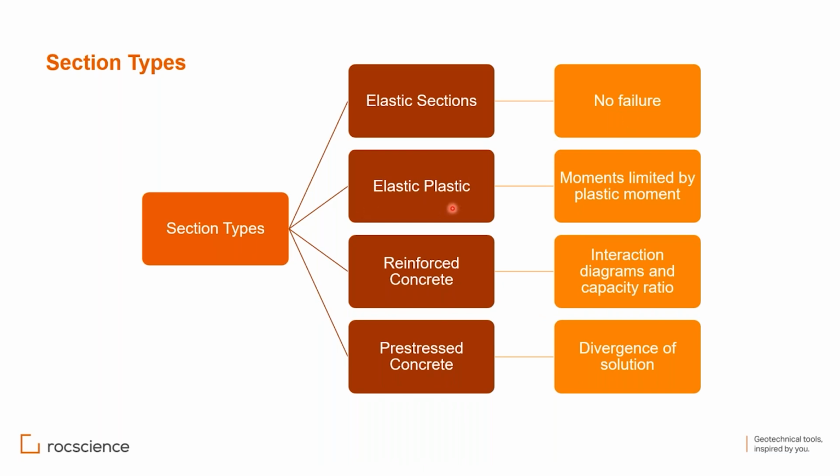In elastic plastic sections, you can apply a limit to the moment capacity of the section. So wherever the section reaches that moment, the program keeps the moment unchanged. The analysis will not add to that moment. So it can be the plastic moment, or the maximum elastic moment, or any moment you want.